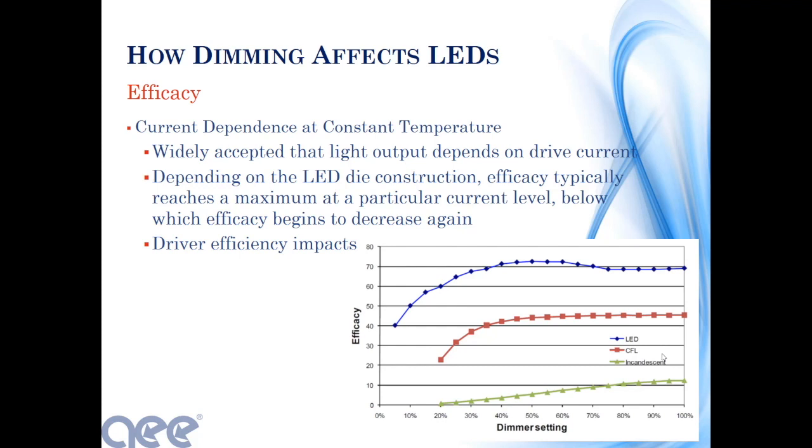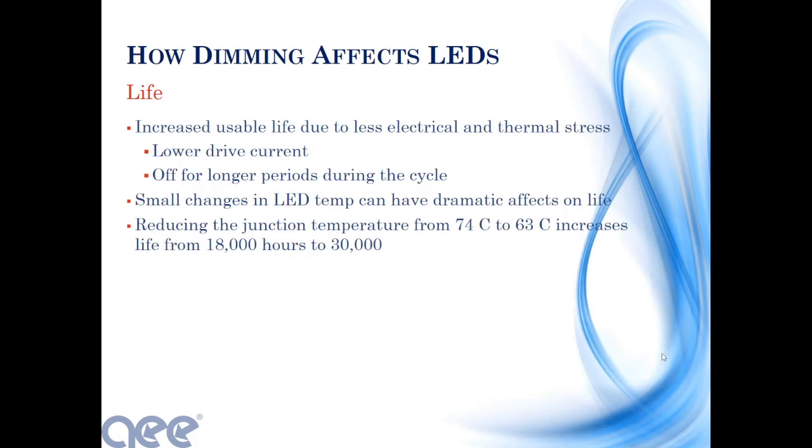The driver efficiency will also have an impact. And we don't talk about driver efficiency often because we like to talk about how efficient LEDs are. But if you have a driver that's not terribly efficient, that will determine how efficient your luminaire is, the efficacy of what comes out of the whole package, not just the LED itself.